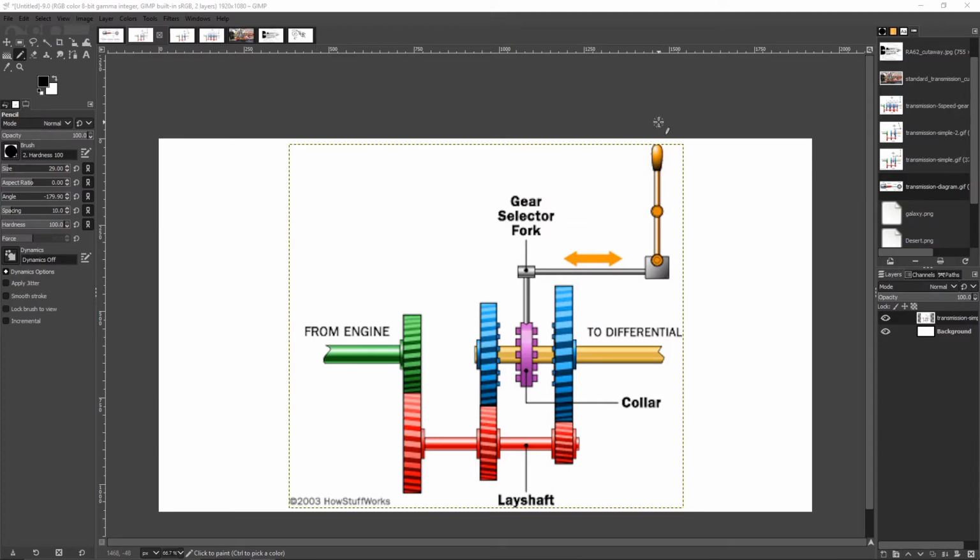So we've got our gear selected. Let's pretend this is a very, very simple engine here. Our transmission input to the counter shaft, and I have a selection here of either first or second gear. So neither of them are actually engaged until you push the gear select fork. And then everybody take your hand out and do the H pattern with me. In order to achieve first, we're going to go left, and your options are forward or backwards, right? So in this one, if this was a transmission in your car, there would be no left. It would only be forward and backward.